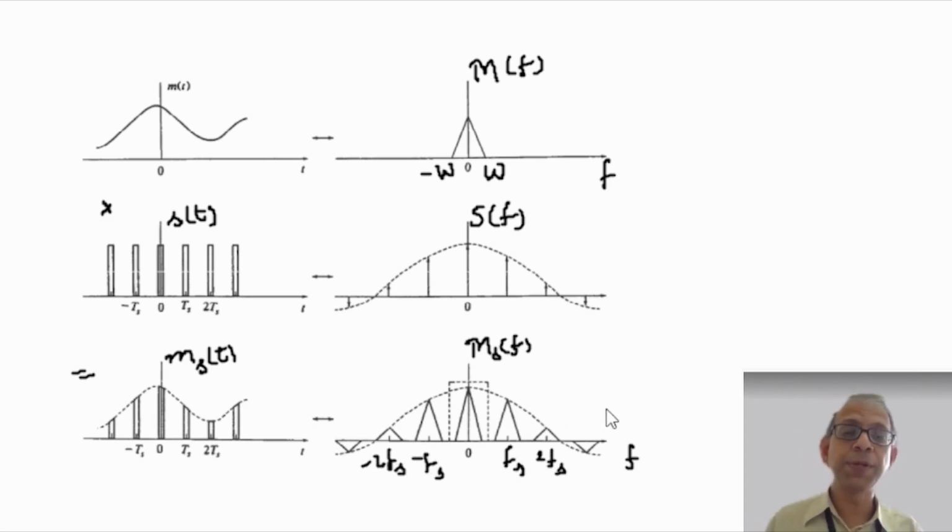The difference compared to the ideally sampled signal here is that the successive copies of the original spectrum M(f) get scaled as per the sinc function, and this is what we get here. Clearly, not all the copies are exactly identical. Their shape is the same. However, they have been scaled, but that is no cause for worry.